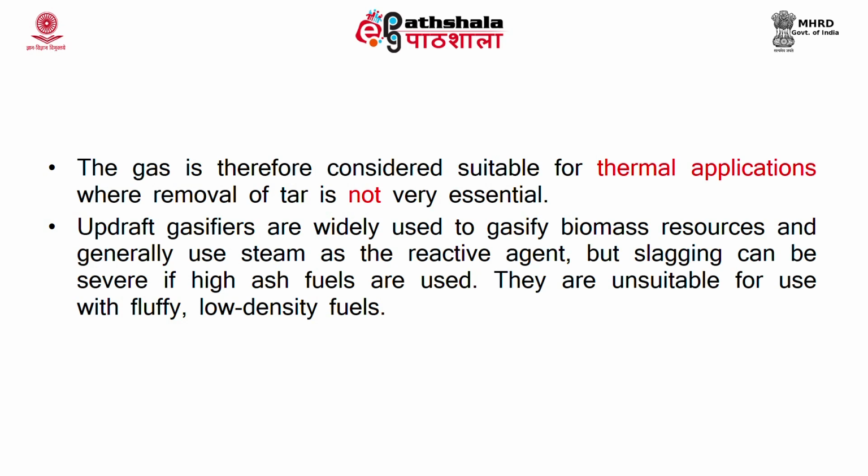This type of gasifier is widely used to gasify biomass resources and generally uses steam as the reactive agent. But slagging can be severe if high ash fuels are used. So, this type of gasifier is unsuitable for use with fluffy or low density fuels.